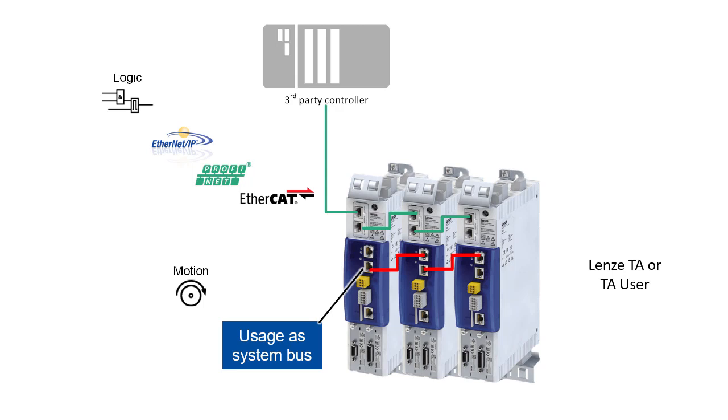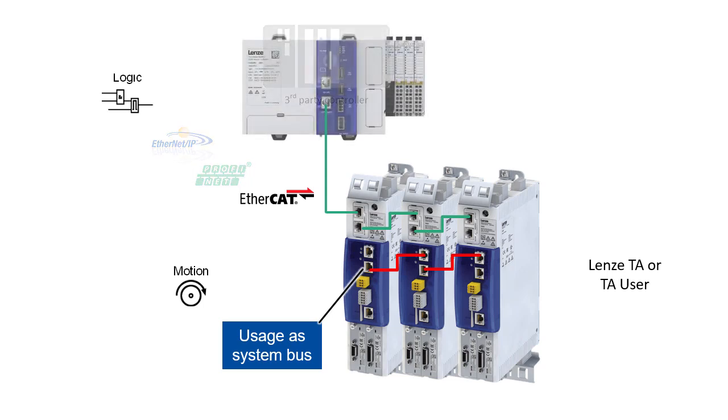The electrical shaft functionality can thus be implemented via the EtherCAT onboard. In this case, the System Bus functionality of the i950 drives provides the synchronized motion communication between the drives. Applied to our application, we use the EtherCAT onboard as the System Bus for decentralized motion control with electrical shaft function. The logic control of all i950 drives is done via the EtherCAT Fieldbus modules.